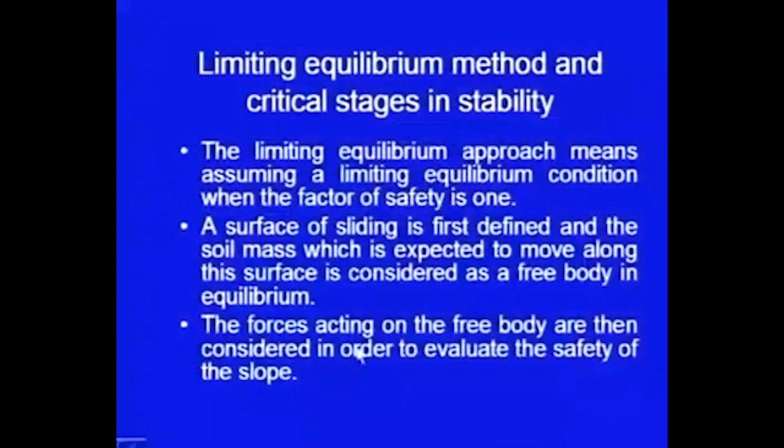Now, the forces acting on the free body are then considered in order to evaluate the factor of safety. That body we consider as a whole mass, as a whole free body, and then its equilibrium is considered, and from that equilibrium we decide the factor of safety.